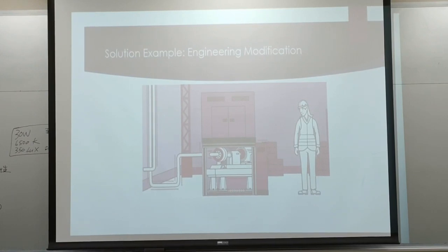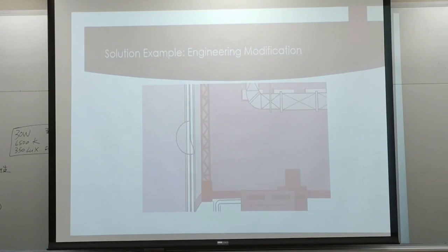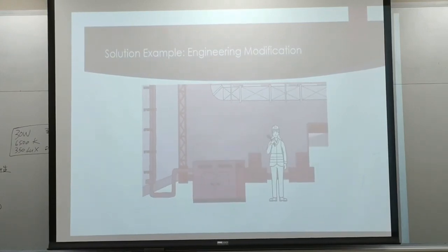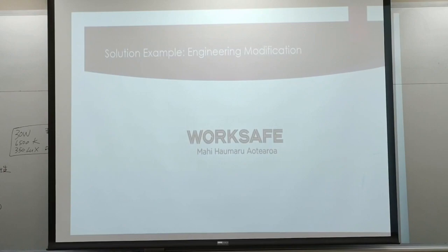There's a bunch of other things you can do to reduce vibration. Use coil springs under the motor to reduce the vibration transmitted from your machine. Vibration can also transmit in pipes and ducts, creating a ringing sound. Line your pipes with sound-absorbing materials to reduce noise. Regularly maintaining or upgrading your machinery can make a big difference to vibration in the workplace. For other ways to reduce the noise and vibrations from your machine, also check out our video on damping.